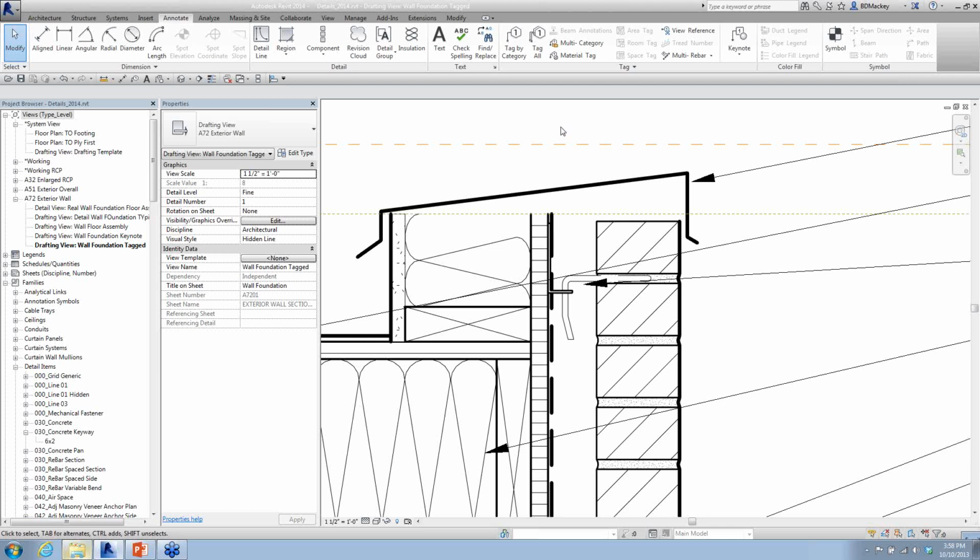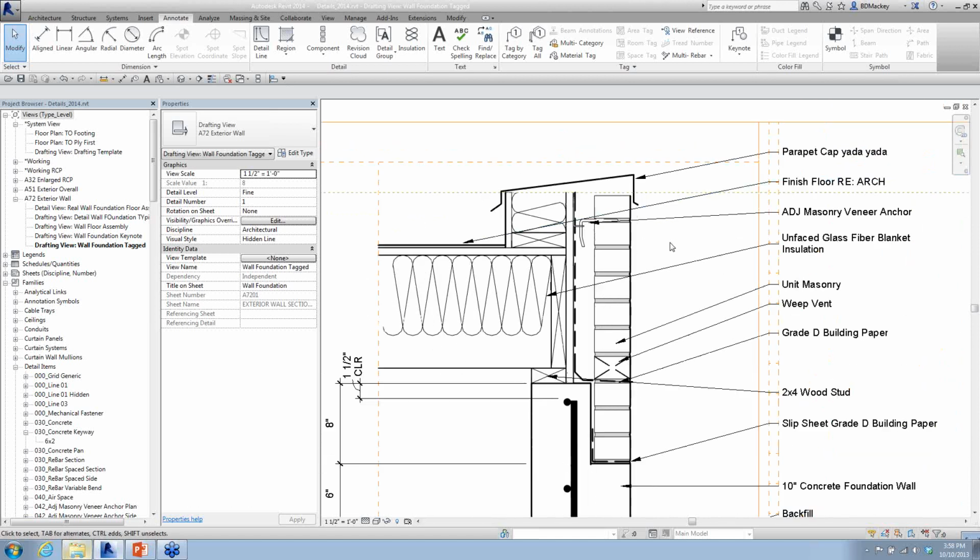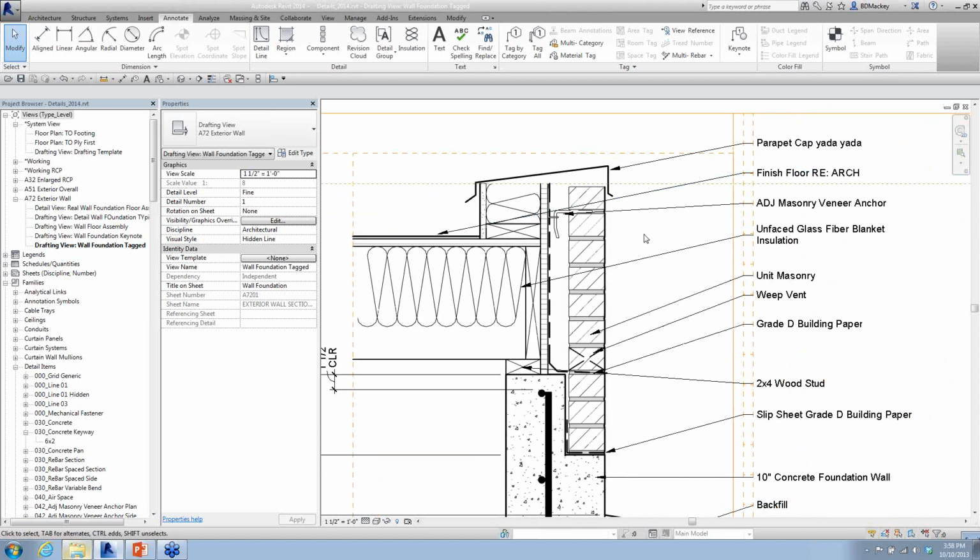Yeah, and it seems to work. Does it work most of the time? In my experience, it has, going from one object or item to another, in sketch mode or out of sketch mode. The only time it doesn't work is if I had drawn model lines. You can't copy model lines and paste them into a detail family. They have to be annotative or symbolic lines. Right. Cool. Detail lines.